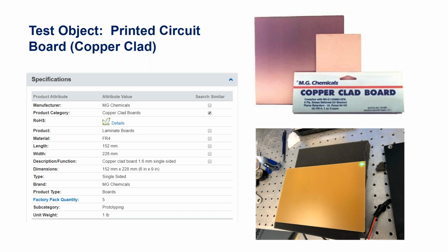What we want to show is a case study where we actually look at this from measuring the structural dynamics and then modeling it and then trying to predict what will happen and then evaluate, okay, if we change anything, how does that affect the sound output? So what we wanted to do together with Siemens is come up with a case study where we can take something that we can model, in this case, a very plain, flat printed circuit board, put a buzzing component on it, and then do the whole process all the way through: testing, modeling, validating the modeling, modal analysis, and then acoustic sound field prediction.